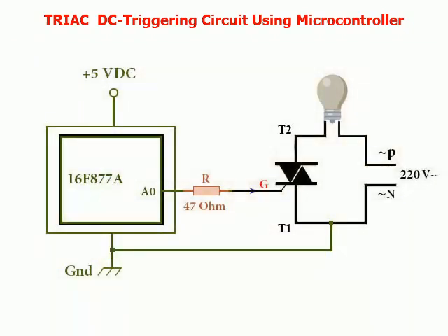Although this circuit works and the TRIAC is triggered fine, it's not ideal, and could be dangerous. The disadvantage of this circuit is exactly this connection between the terminal T1 and the ground of the 5-volt DC power supply, which results in a direct connection between the 5-volt DC power source and the high-voltage 220-volt AC power source. This direct wired connection between two power sources, operating at two extremely different voltage levels, 5-volt DC and 220-volt AC, is very dangerous, especially when working with high power loads, where voltage and current levels may reach high values, and may cause critical damage to the electronic circuit components.